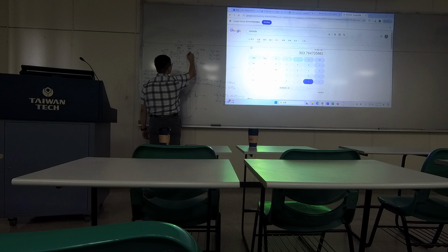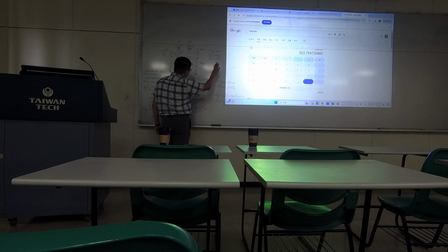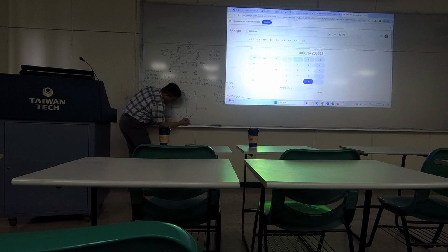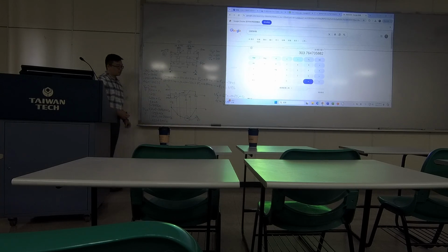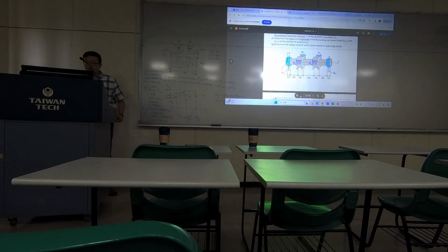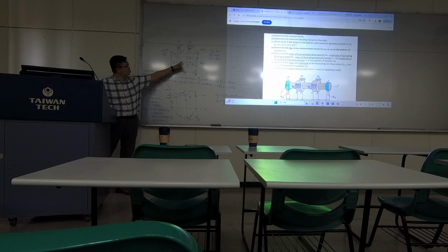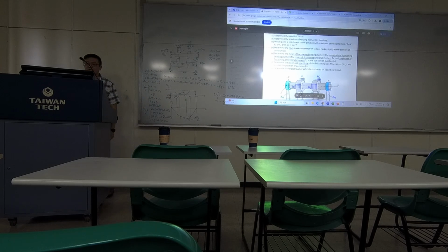So somewhere here, like this corner is 300. So 4 millimeters to the right, that's where you have the extreme value. So right somewhere here. That's the worst bending position, the position with the largest bending moment. Okay, that's how you can get the maximum bending, next to the position of 300 millimeters.